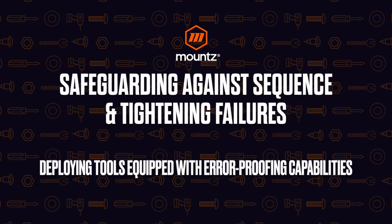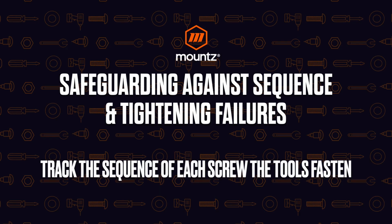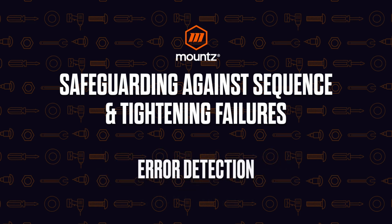So the first one, we want to be able to use error proofing capabilities within a particular tool. So we can make sure that we can track each sequence of the screws during the fastening process. And this is going to help us monitor and track through the process, making sure that all of the fasteners get torqued and that they get torqued correctly. And if there is the ability to have error detection as we move through that, again, if there is an error, we can go ahead and address it right when it happens, and we can go ahead and fix it and then move on through the process.